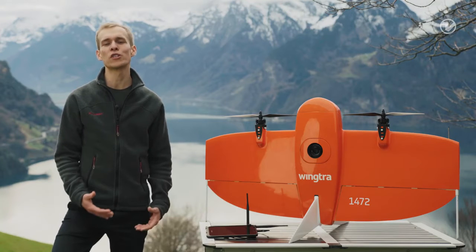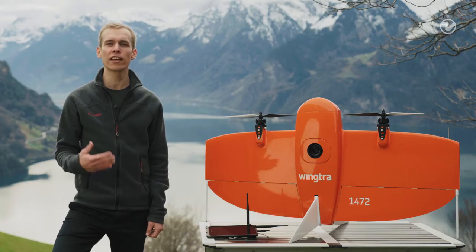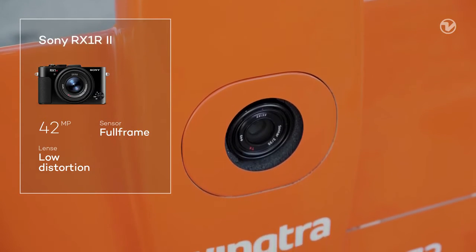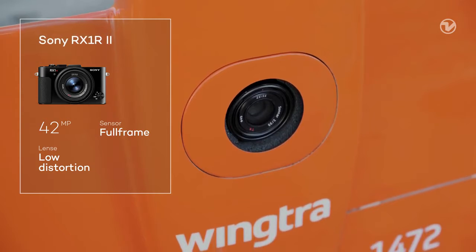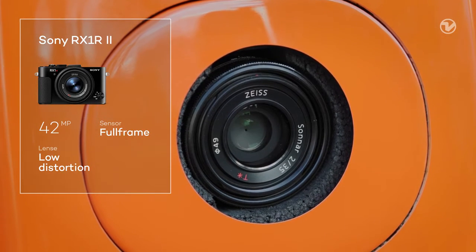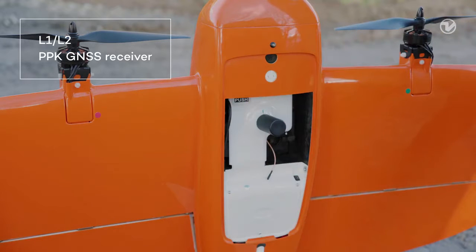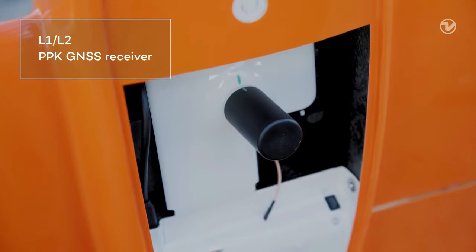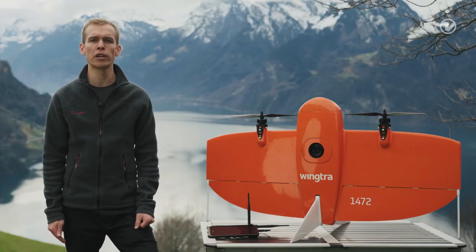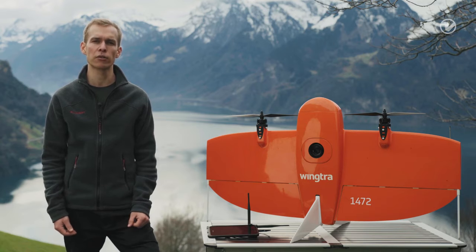WingtraOne is perfect for this job, as it's a fixed-wing drone offering large coverage that can still take off and land vertically. It carries a high-resolution Sony RX1 R2 camera with 42 megapixels, a full-frame sensor and a low-distortion lens. Then, below the top cover, you can see where the magic happens. This is a GNSS PPK module. Together with the data of a continuously operating reference station, it will geotag our images with centimeter-level accuracy.